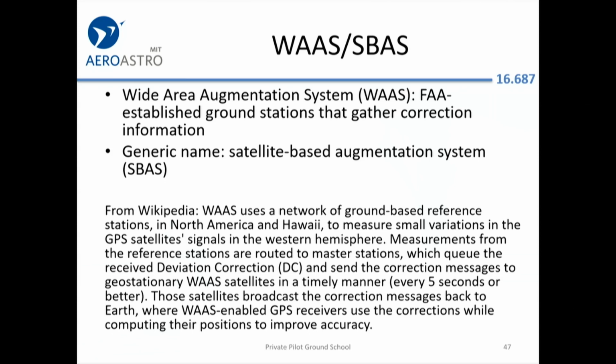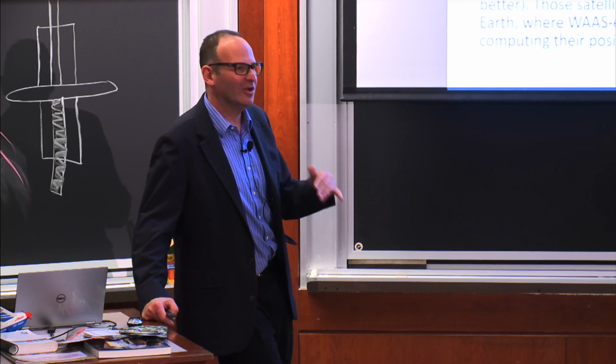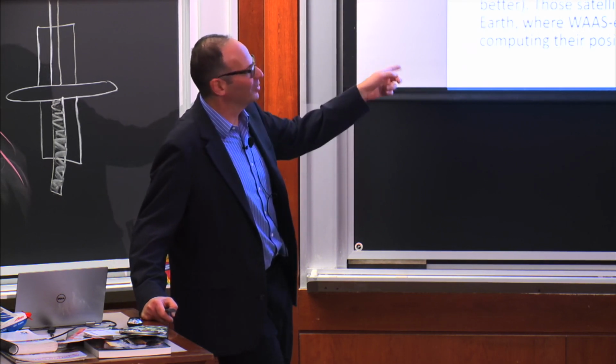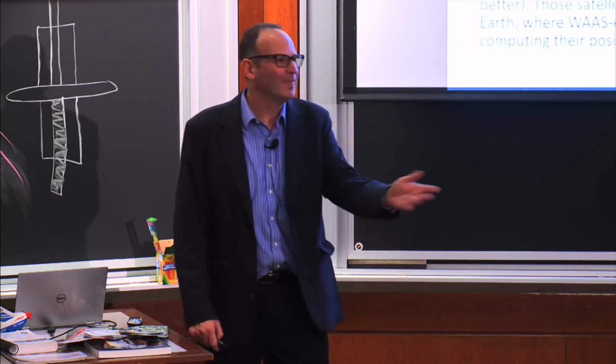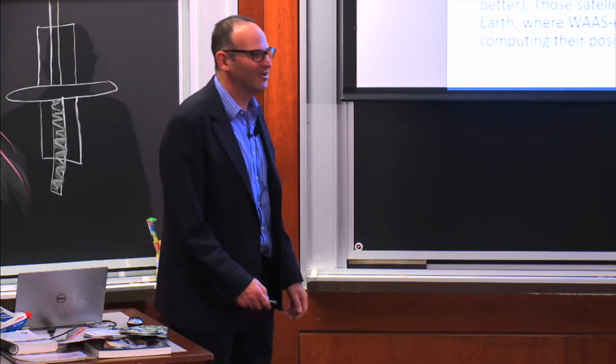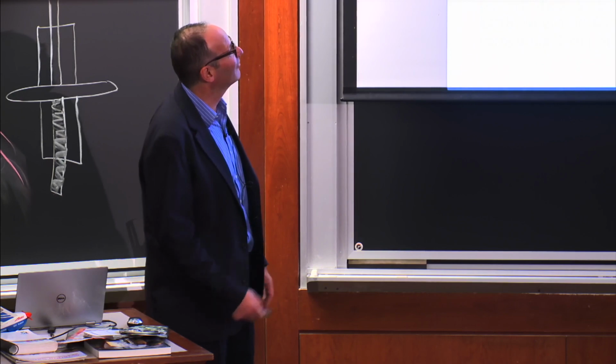You can get accurate enough to actually fly down right towards a runway. So the GPS system, which launched in the mid-90s, enabled the moving map, and you never were lost again. You always knew where you were. But the WAAS system is what enables these GPS approaches where you navigate in 3D, to within 10 feet or something of precision right down to the runway.